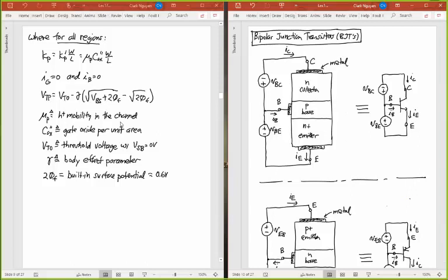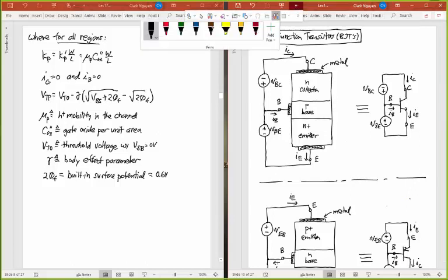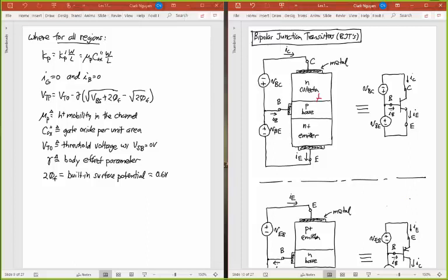But effectively, I've created back-to-back diodes here. And so I can draw that to emphasize that. I got a diode here. I got another diode here. And they're back-to-back. And so it looks like you're never going to get any current out of this. But in actuality, you can get current depending on what voltages you put between this P and that N and this P and that N.